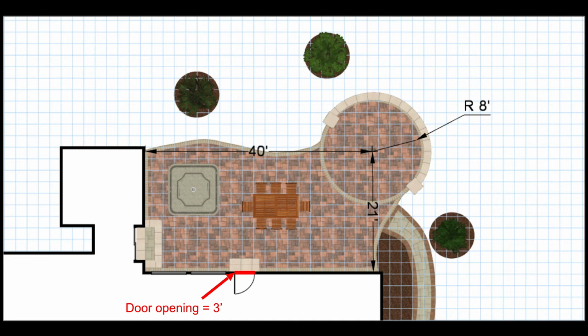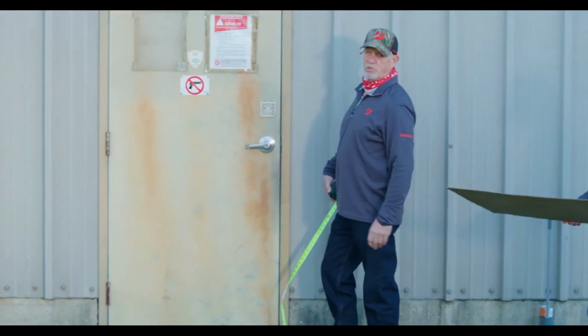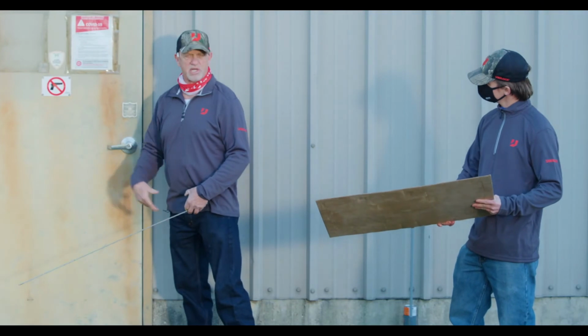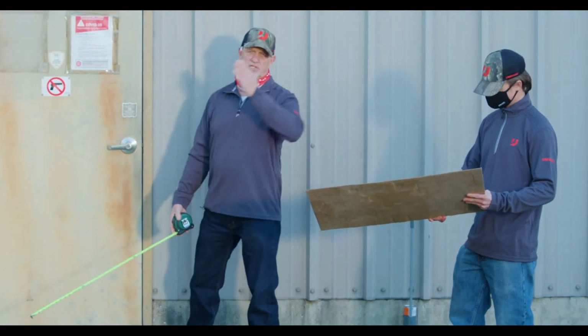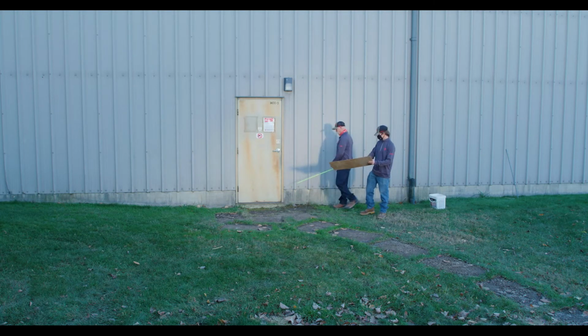That door shows 3 feet. 3 feet. At that point. And we'll double check our measurement here on this door opening. And we're at 36 inches on this door opening. So this is our starting point basically for our job site layout. Now I want to establish that X coordinate in that direction against the foundation of the house. Jim, if you'll hold that tape measure here.